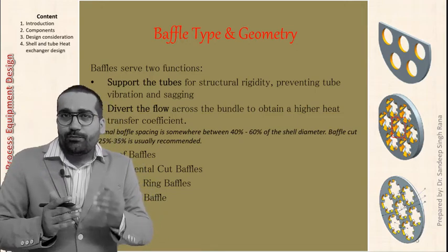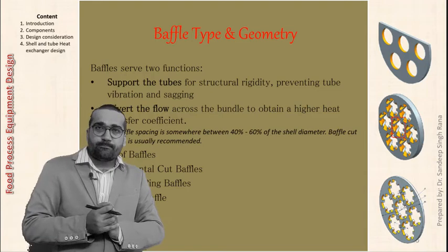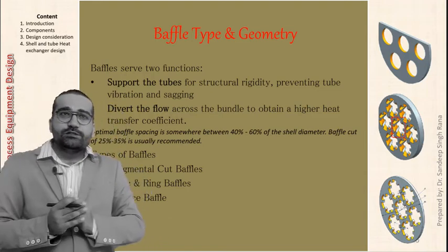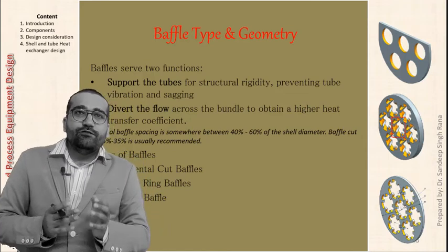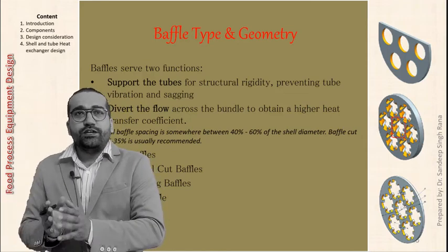And how do we optimize the baffle spacing? Baffle spacing will generally be 40 to 60% of the shell diameter.